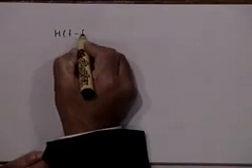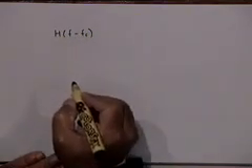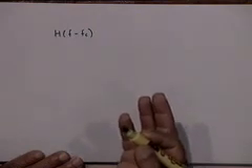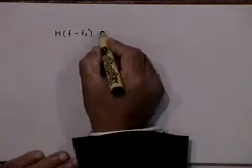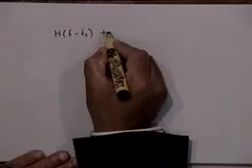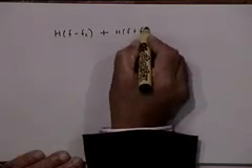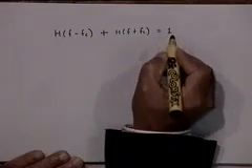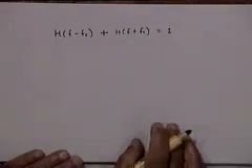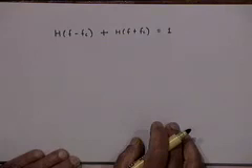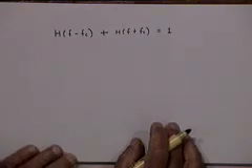And the constraint we derived was this equation, that the filter H(f), which is the vestigial sideband filtering filter, must satisfy the condition that H(f − fc) + H(f + fc) must be equal to 1, right? This constant 1 of course is arbitrary, it could be any other constant. Main thing is it is a constant value.